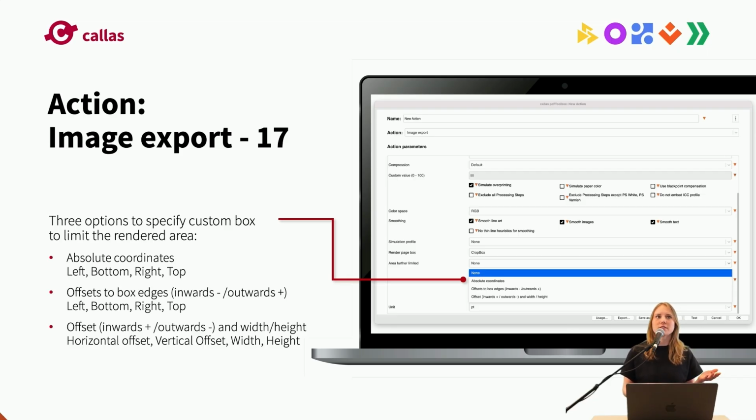The first one, of course, absolute coordinates, remains, but in addition, you can also specify the area using an offset to the box edges. So you can set the offset for each page edge individually, moving them inwards using negative values and outwards using positive values. And the last option is to specify a horizontal offset and a vertical offset, and a width and height for the custom area.